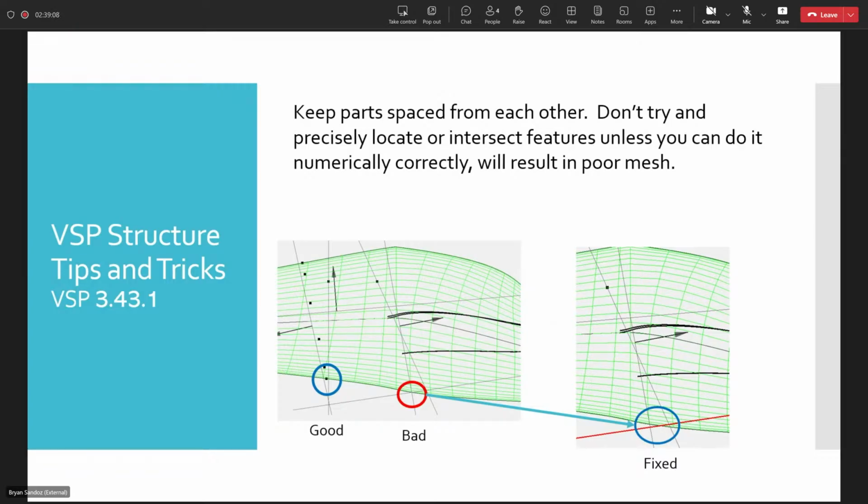Again, with making things perfect, you may be like, well, I don't really want the floor exactly there. It should be a little bit higher, a little bit lower in reality. And yes, you will be able to do that later in reality. But for this process, just put it relatively close. You might have to do that to get away from meshing issues, because the methodology here is about speed and getting a very complicated mesh built really quickly. That's a rough or coarse approximation of your structure.